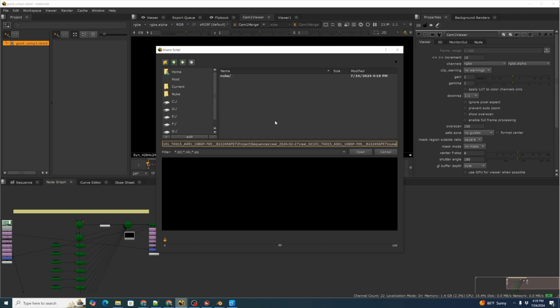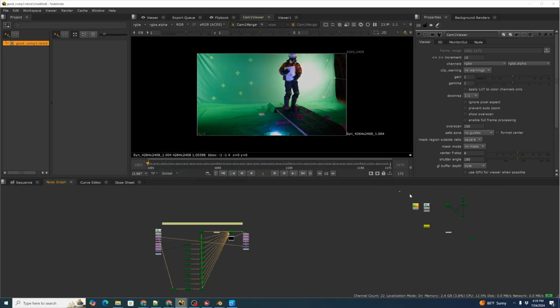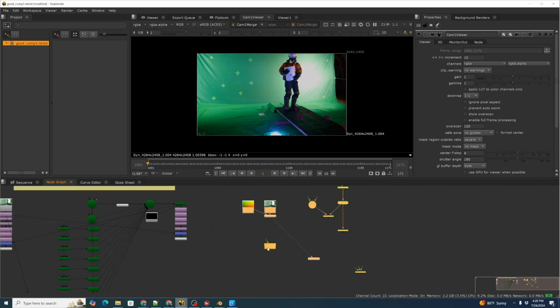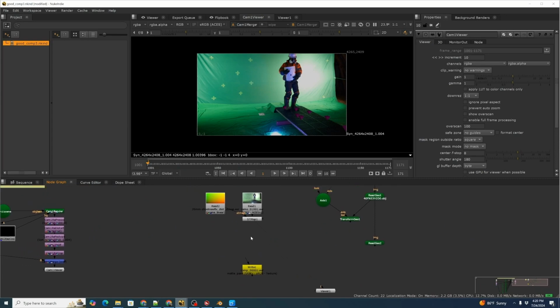And let's go ahead and hit paste. And that brings us to a Nuke directory. And there is our Nuke script that Autoshot generated. We can open this and we can see where it created some nodes. So let's grab our nodes and bring them all fairly close together so we can see what's going on. And this is a set of nodes that Autoshot generates. And it has a couple of other pieces that are very useful.